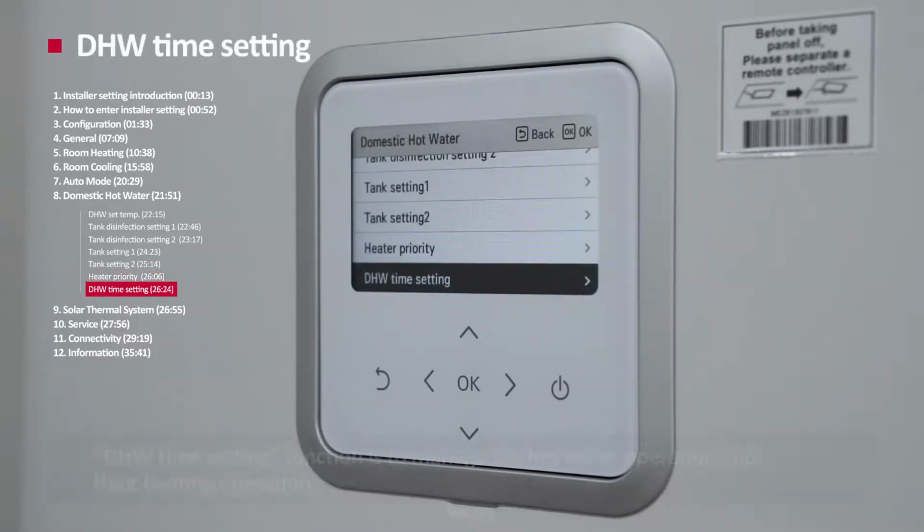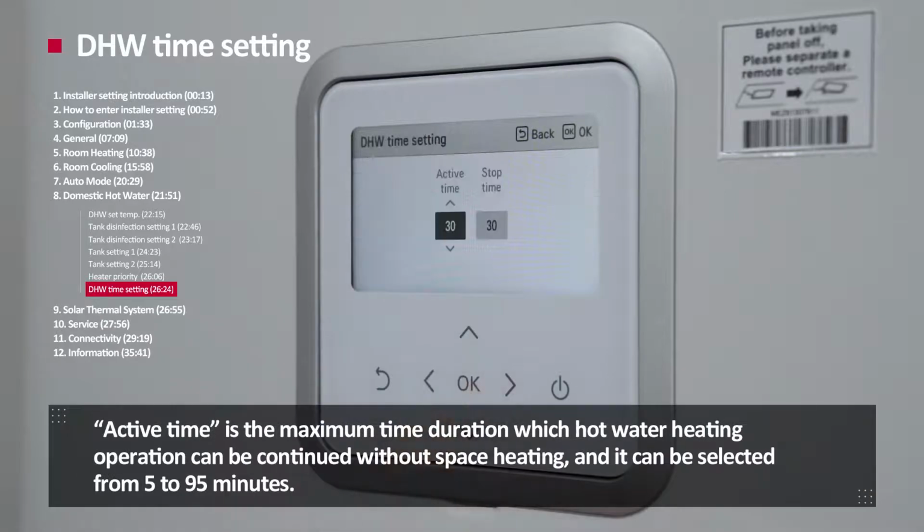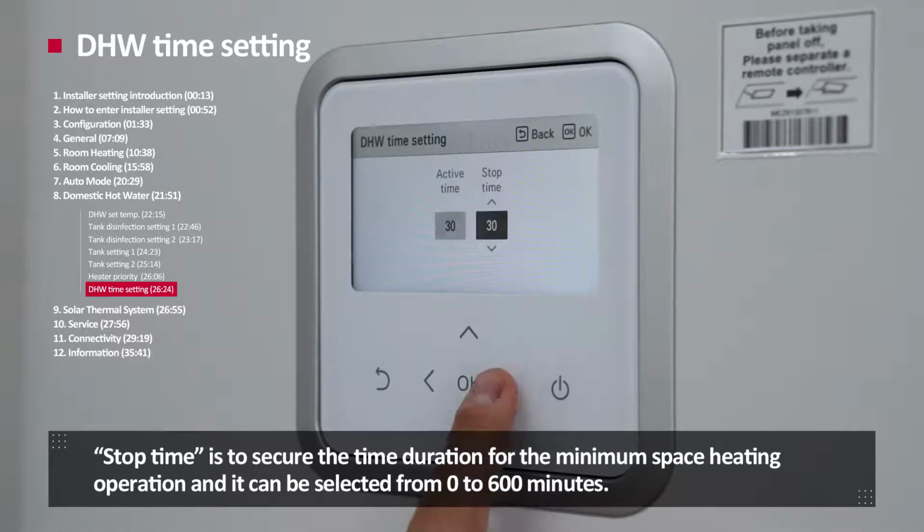DHW time setting. DHW time setting function is to manage the hot water operation and floor heating operation. Active time is the maximum time duration which hot water operation can be continued without space heating, and it can be selected from 5 to 95 minutes. Stop time is to secure the time duration for the minimum space heating operation, and it can be selected from 0 to 600 minutes.